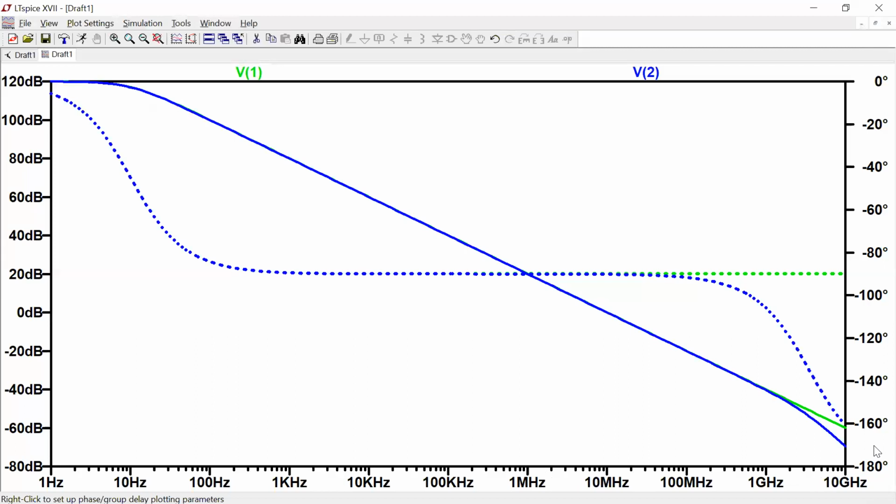In this case, it's not underdamped. There's one pole up here, one pole way down here. It's so separate that it isn't until here that you can tell the difference between a first and a second order system. But sometimes you can put in some feedback, it manipulates these poles, and the next thing you know, your op amp starts to behave underdamped, and so it starts bouncing around all over the place.